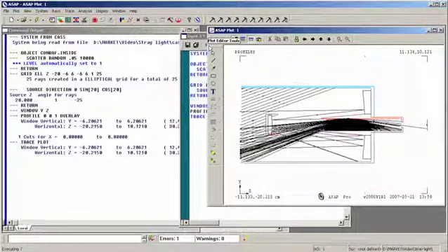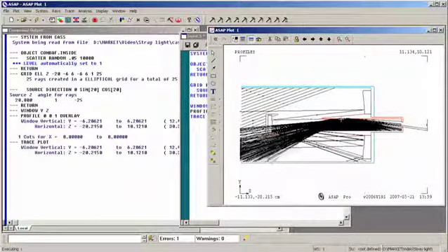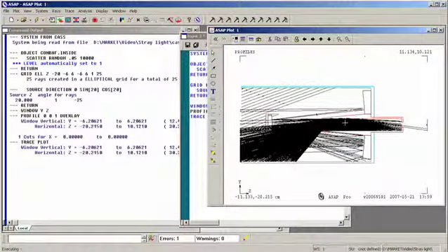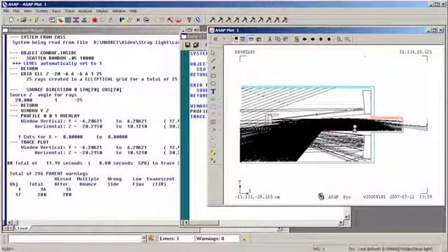Here's our ray trace. We can see some of the rays have hit the conical baffle, and we can see many scattered rays coming off of this conical baffle, scattering into the hemisphere over that interior surface. Now we see our first problem. Even though we've asked for very many scattered rays, 10,000 scattered rays for every incident ray, none of those rays actually got to the detector. We're going to end up with no power whatsoever on our detector, in essence saying our stray light is 0, which is the wrong answer. We have two fundamental problems with what we've just done. First of all, we're wasting rays.